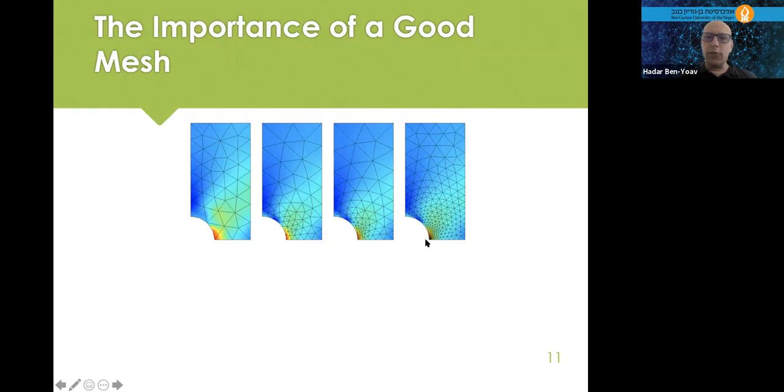We shouldn't have a very dense mesh everywhere, because then the calculation takes years. We actually need to use our common sense and know where the changes should be very small, very high resolution. Then over there we should put the dense mesh. In places where we don't have a big variation, we should use the less dense mesh.